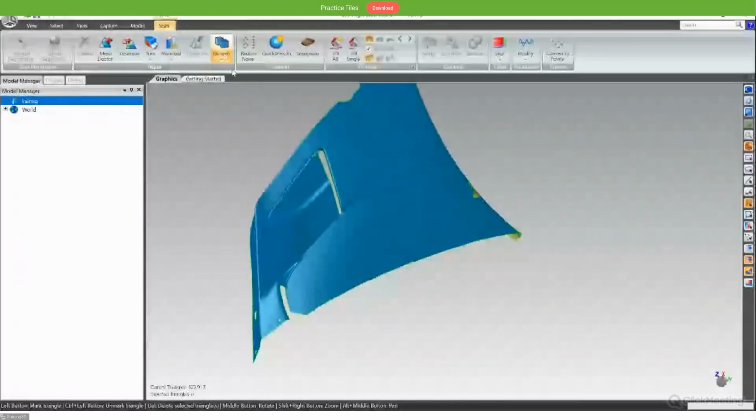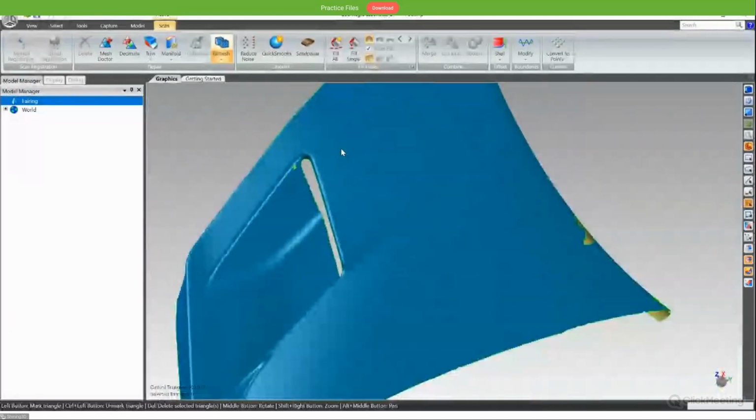So the remesh function provides remesh, refine, rewrap, repair normals and flip normals. Okay, for a 3D model, with remesh all the triangles will be recalculated, and refine increases the number of triangles or polygons, so the details will sometimes be improved. Rewrap recreates the polygon mesh. Like I select this area and rewrap, so it will only remesh the selected portion.